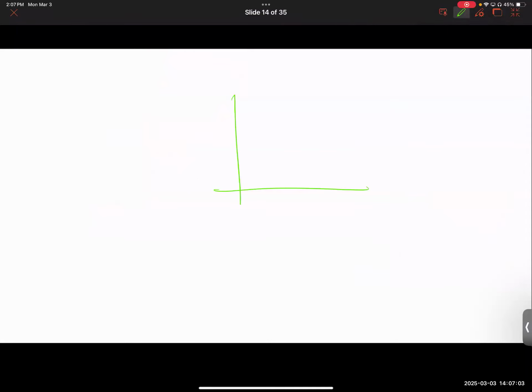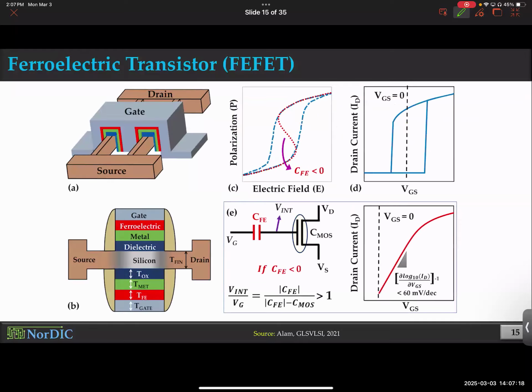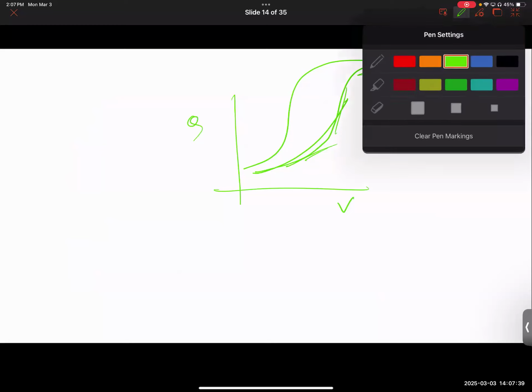Okay, similar to that, capacitance. Let me talk about capacitance. We just discussed that the Q versus V characteristic gives you, if you take dQ over dV, the capacitance, right? We use that to measure the capacitance for ferroelectric, remember? To take the slope everywhere. But just notice, in a ferroelectric material, just look at the conventional ferroelectric hysteresis. No matter where you go, notice the slope is always positive. Don't you think? No matter where you go, it's always positive. Okay, sure. Ferroelectric material always gives you positive capacitance, it looks like. And so does most other materials.